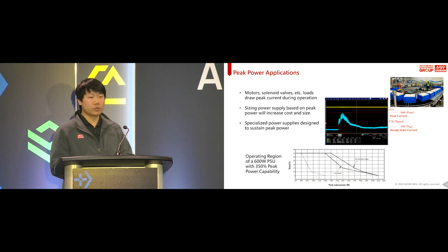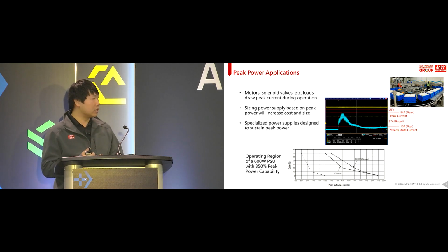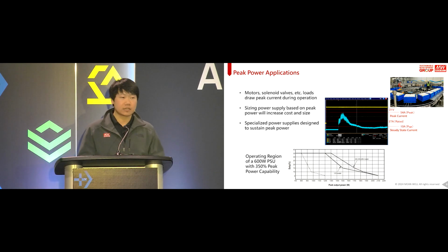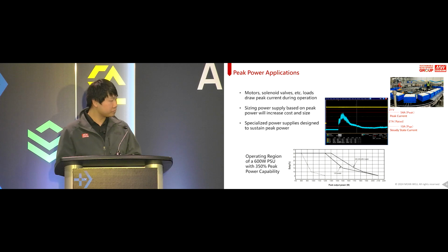However, in recent years, we've started to develop power supplies that are specially catered towards peak power applications. So we can have power supplies that are rated for 300 watts, that are able to sustain up to 1,000 watts of peak power. And that helps with the sizing and selection of the power supply. So you don't need to size a 54 amp power supply just for a 10 amp steady state current application.